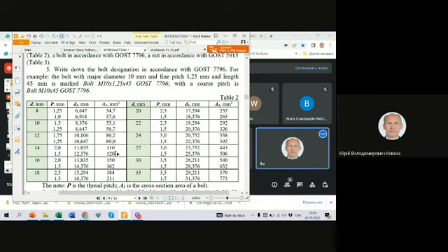Okay. So when we know both dimensions we have, we can calculate the joint constant. Remember, we used joint constant to find prestressed force and to find Fz. And in both cases, we use a recommended value. But when we know diameters, we can calculate the correct value of joint constant. Let's do it.